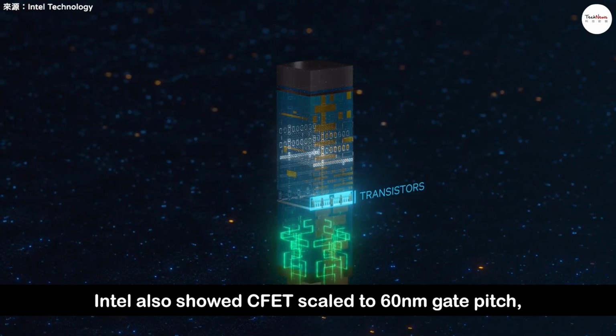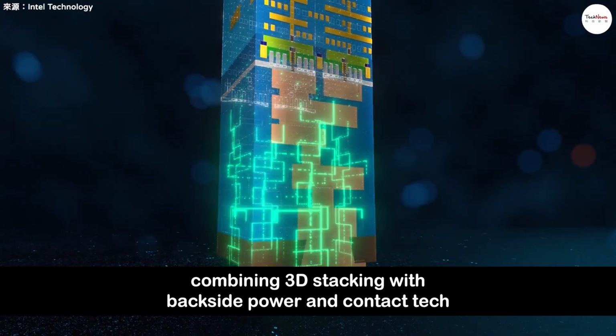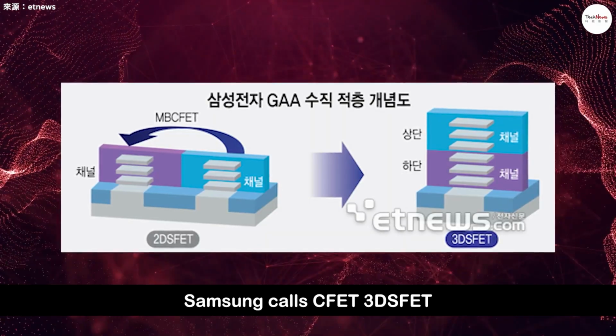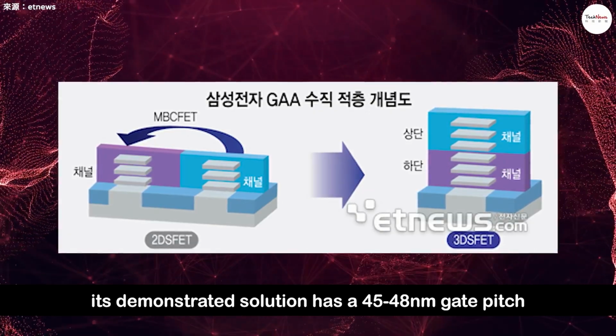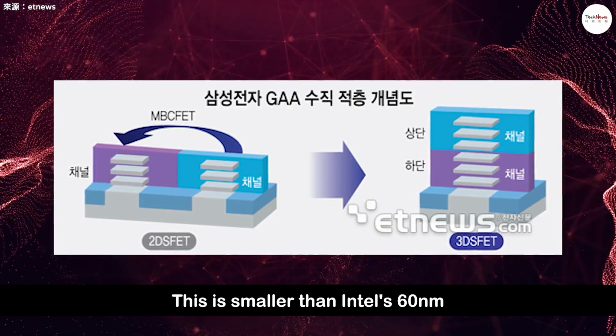Intel also showed CFET scaled to 60 nanometer gate pitch, combining 3D stacking with backside power and contact tech. Samsung calls CFET 3D FET. Its demonstrated solution has a 45 to 48 nanometer gate pitch. This is smaller than Intel's 60 nanometers.